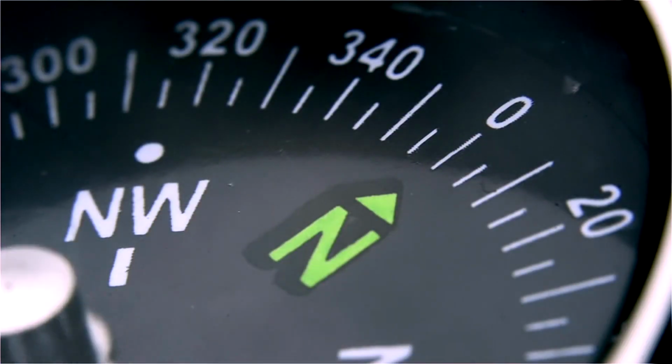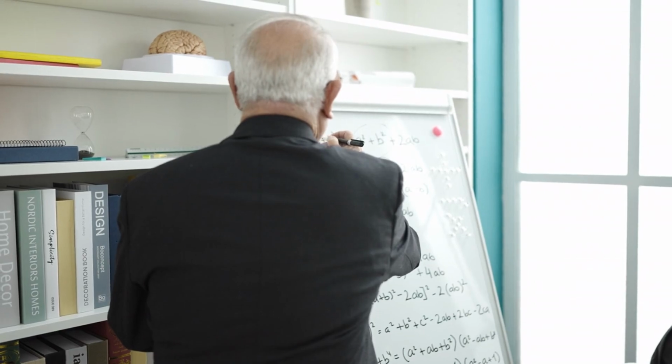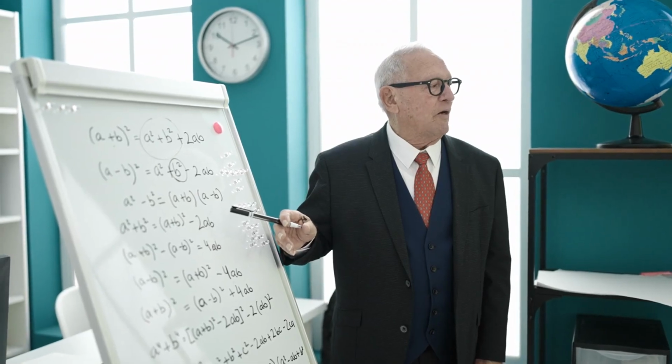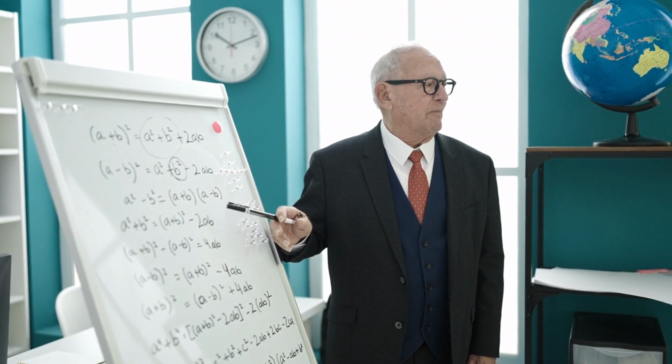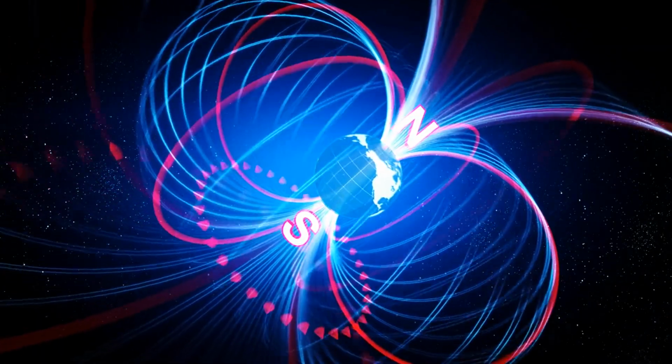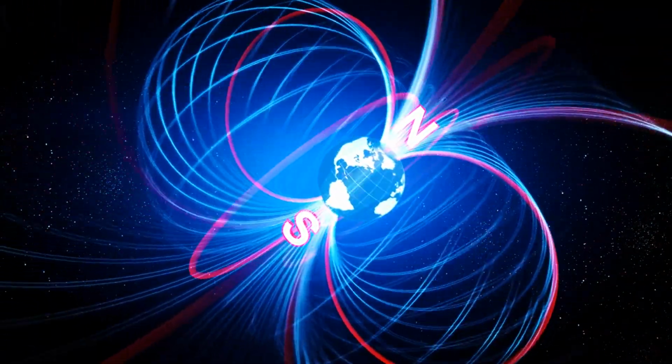Variation East, Magnetic Least. Variation West, Magnetic Best. Here are some examples to try. 1. Your true course is 040 degrees T. The variation is 23 degrees E. What is the magnetic course? 2. Your true course is 090 degrees T. The variation is 10 degrees W. What is the magnetic course?